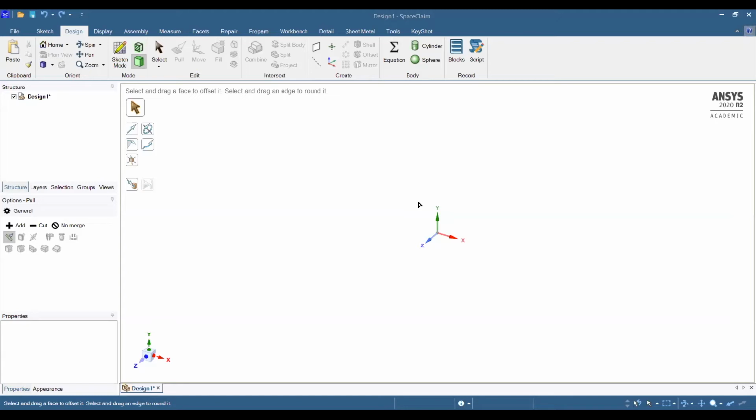I also want to draw a comparison to SolidWorks because I know many of you might be familiar with that program as well. SolidWorks is regarded as a feature modeler, in that it has a feature tree on the side where you can select and edit your individual features. For example, if you made an extrusion halfway through your modeling process, in SolidWorks you can go back to that extrusion feature and edit it if you wanted to.